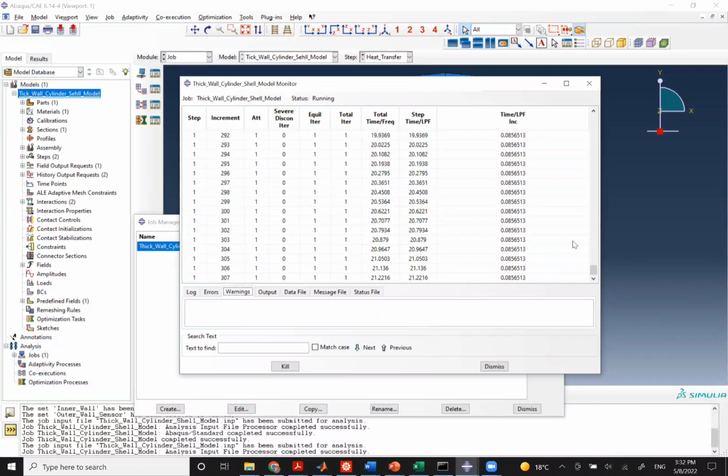But in simulation, if you're not sure, that might take trial and error to choose the right time. Since I've done that before, probably 1,000 seconds will be sufficient to reach the steady state solution for this problem here.